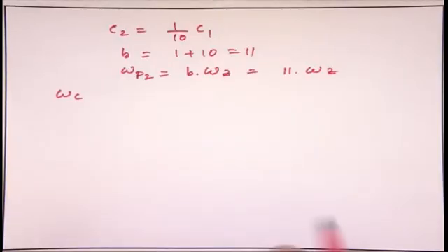Okay? So you want the wandering of the delta phi, or the locking, to be done within a specified amount of time, and also there should be less ripple at the control voltage. That means your locking time will dictate the actual bandwidth. Lower bandwidth means a higher capacitance of the loop filter, so delta phi cannot change too much; it is very sluggish.